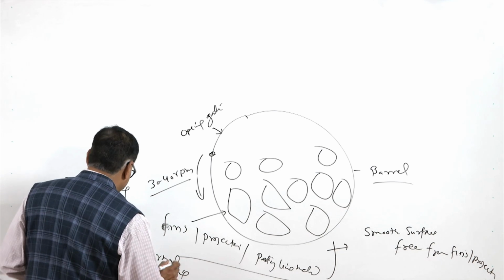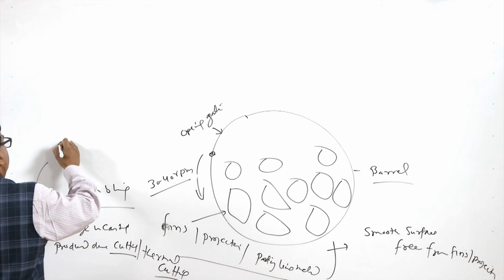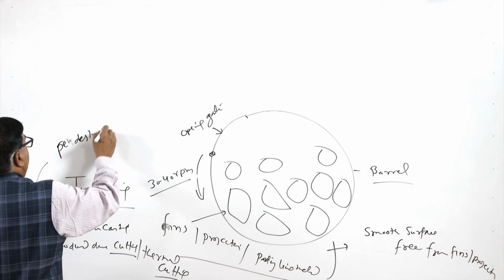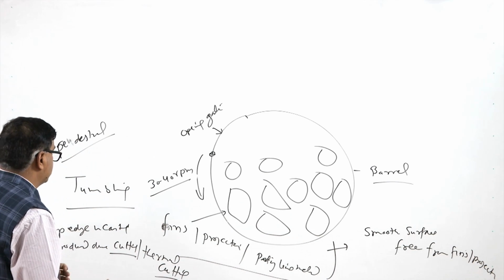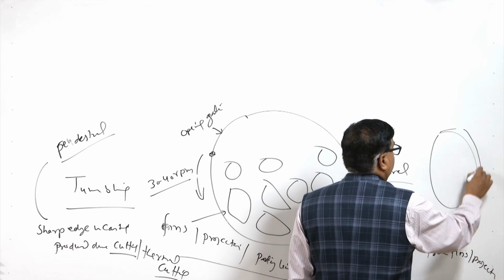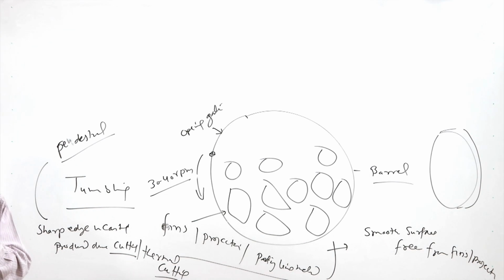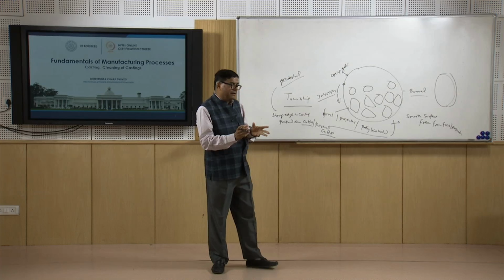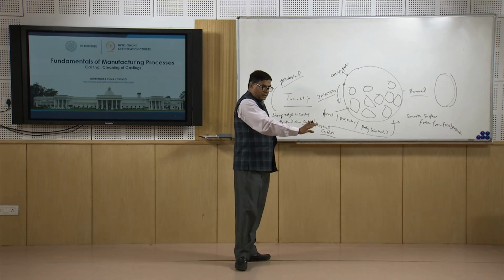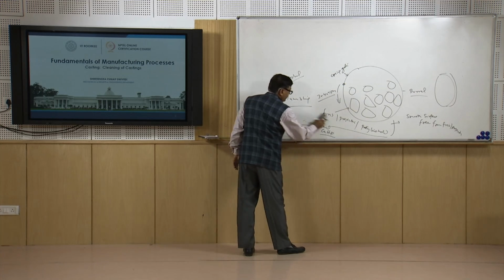these sharp edges can be easily polished using, depending on the size of the castings, a pedestal grinder for the small size castings. Basically the casting is held in the hand and it is pressed against the rotating grinding wheel. Another method is that if the casting is really big in size, then the swing type of grinder is used, which is pressed against the casting. It can be moved easily and brought near to the casting, and it is pressed against the surface which is to be smoothened or finished.